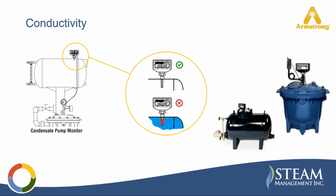Now, while conductivity monitoring is commonly associated with Armstrong steam traps, the technology can be used for other applications as well. One example is condensate pumps and receivers. In these systems, conductivity probes can be used to monitor liquid levels and detect abnormal operating conditions. For example, if a receiver begins flooding or condensate levels rise above the expected limits, SteamEye can provide an alarm so maintenance personnel can investigate the issue before it affects the system operation. This gives customers additional visibility into critical condensate management equipment beyond simply monitoring steam traps.